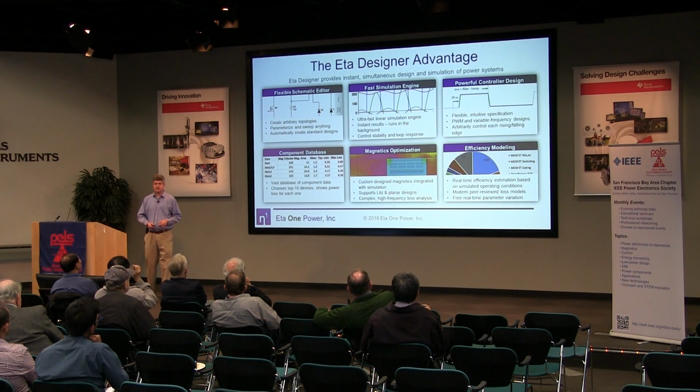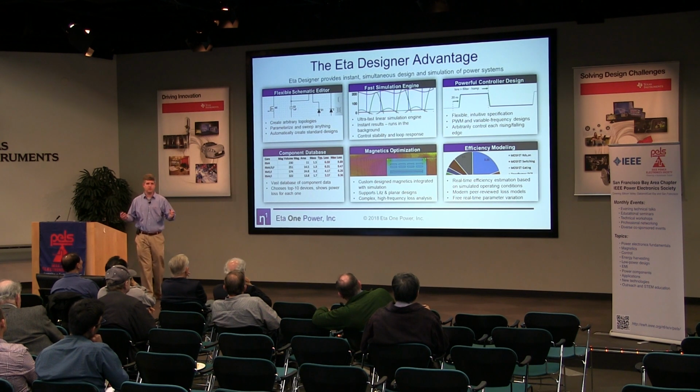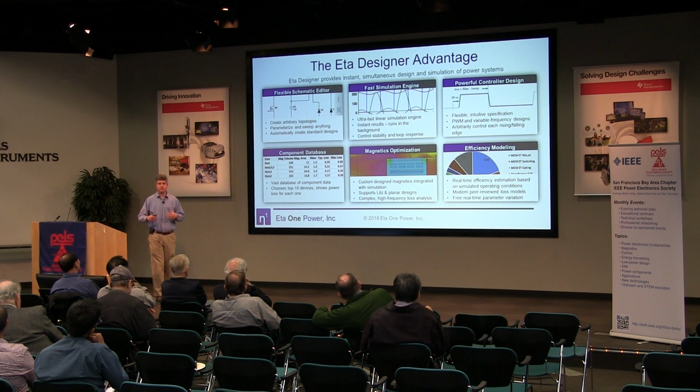What ETA-Designer does is a bunch of things. It's trying to wrap all these into one product, into one piece of software. So we start with a flexible schematic editor, so you can create whatever topology you want. You can start with a buck. We can actually automatically design a buck for you with input and output voltages. But you could also design a custom LLC converter or full bridge LLC or whatever you come up with. You can draw it and you can simulate it.